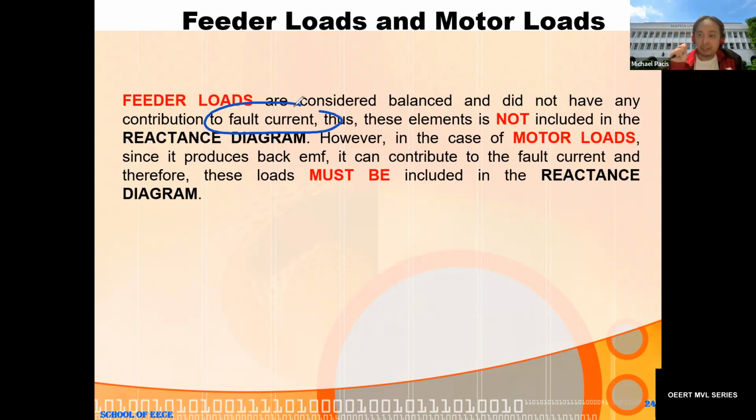So again, the only parameters that will be connected to the reactance diagram are those motor loads or rotating loads. If you see a feeder load, an open-ended load, you will not connect it to the reactance diagram in the calculation of the Thevenin's reactance up to the fault point. So we can have that example here.